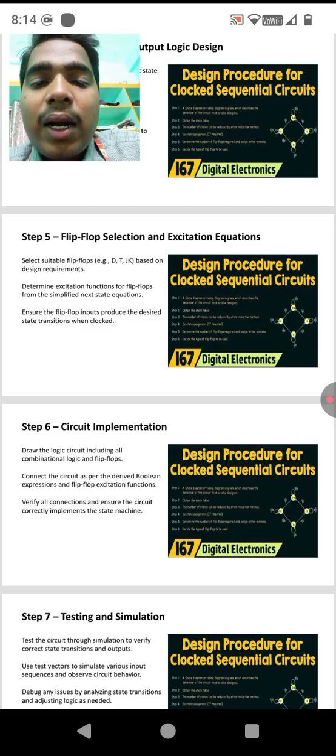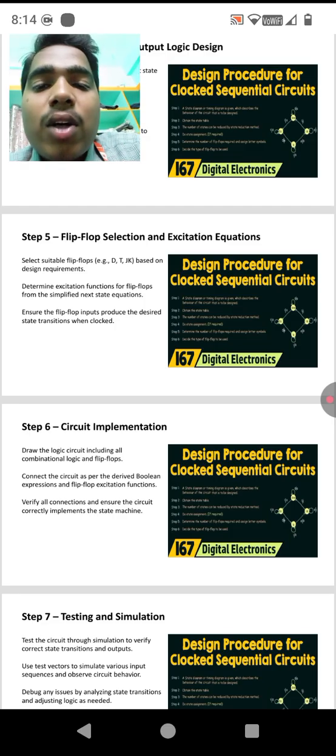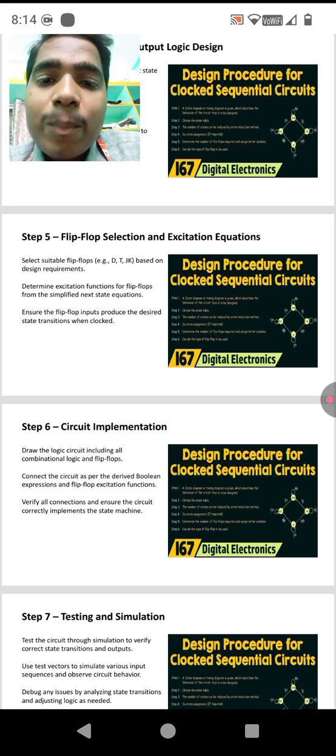Step 5. Flip-flop selection and excitation equations. Select suitable flip-flops. Example: D flip-flop, T flip-flop, JK flip-flop. Based on design requirements, determine excitation functions for flip-flops from the simplified next state equations. Ensure the flip-flop inputs produce the desired state transitions when clocked.